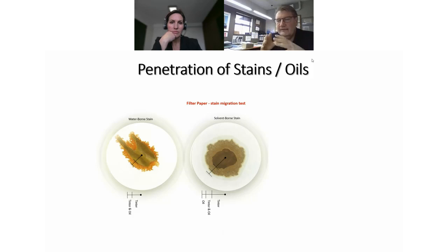So you can see that the oil-based is a smaller particle, so it spreads further, but also oil-based stains take longer to dry, and it can only penetrate when it's wet. So on the left-hand side, everybody's in a hurry, and they use the waterborne stains. And while they do penetrate, they can only penetrate when they're wet. So if they dry in half an hour, you only get half an hour's worth of potential penetration, and a little bit of oil left over keeps on going back. Anyway, the oil-based stains, they penetrate a lot further. They're smaller molecules, so they squeeze into those broken cells, so you get a little bit more penetration.